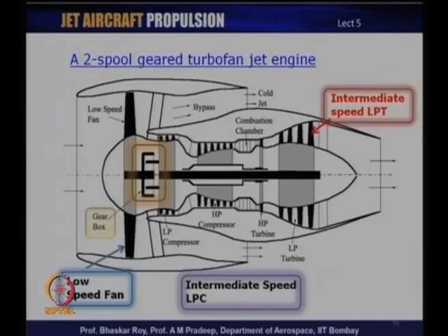They have a geared turbofan, and this geared turbofan allows them to go to very high bypass, and as a result all the benefits of a very high bypass can be obtained by producing this kind of engine. You need a gearbox now, very similar to turboprops or turboshafts, to run the turbofan. So, now we have gearboxes not only inside turboprops or turboshafts, but also inside the modern turbofan engines.